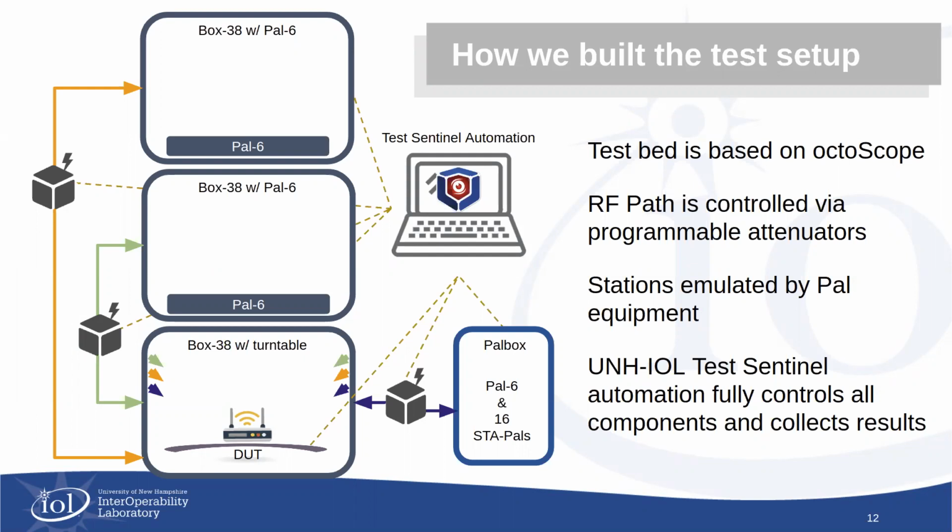While that's good, and obviously necessary for some types of testing, it wouldn't take into account the design of the device under test, its antenna designs, or the placement of those antennas on the device. It would prevent you from looking at the device's spatial consistency, or how it performs as we rotate it through. So we're doing that RF path inside the chamber. We're using near field antennas to couple that air gap to the device under test before we get into that cabled environment between the chambers.